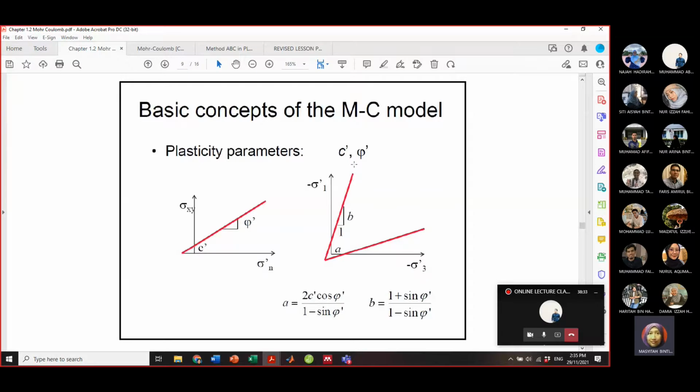If you remember, the yield criterion has a hexagonal shape. So the hexagonal shape from here actually represents the criterion for the Mohr-Coulomb model. If you want to get the usual strength parameters, this is what we commonly plot. We have shear stress and normal stress. These are the parameters you always meet, C and phi. However, when you analyze using numerical software, this is what is calculated in the software using A and also B.